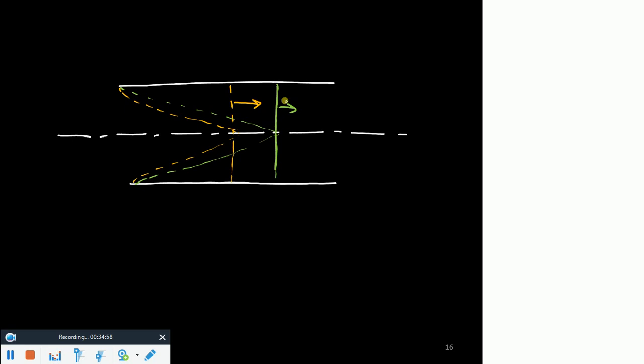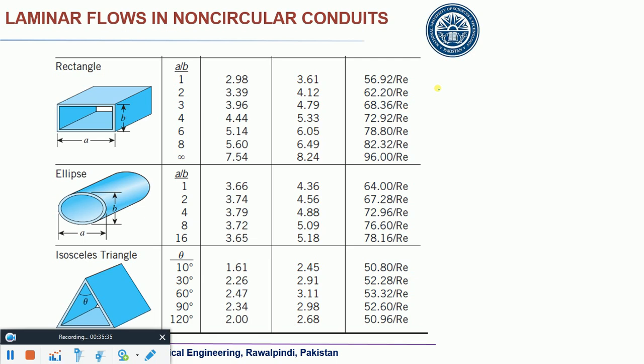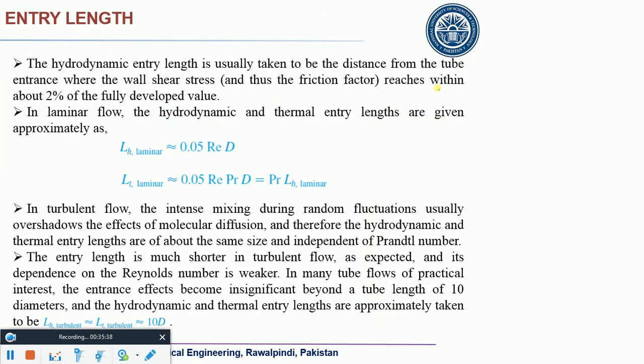And beyond this point you would have both thermally fully developed and hydrodynamically fully developed region. So generally you would call this region from this point onwards as fully developed region. Otherwise you will have to specify what kind of fully developed it is. Do you understand that? Otherwise you would have to define whether it is hydrodynamically fully developed or thermally fully developed. These things are used in the design of pipes. Be very careful about these things. So I just wanted to explain that point.